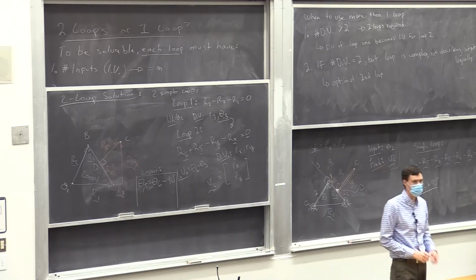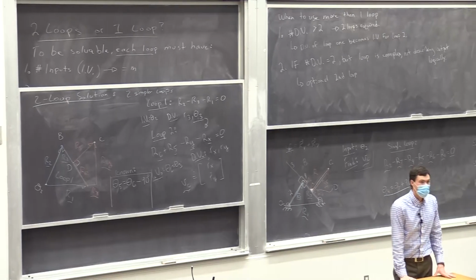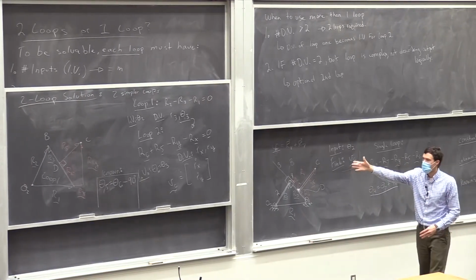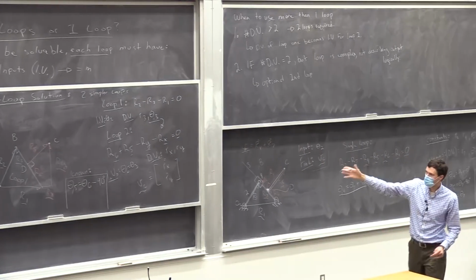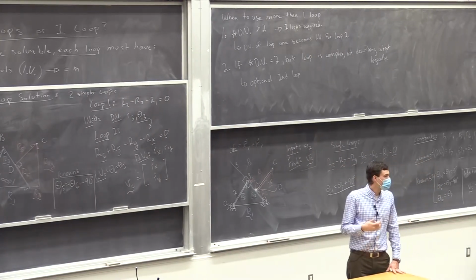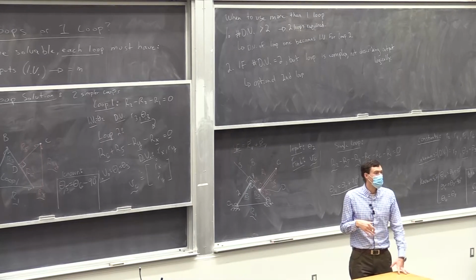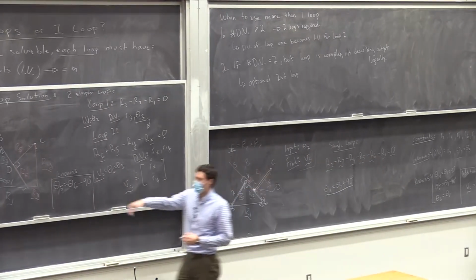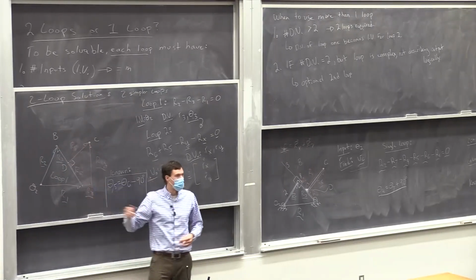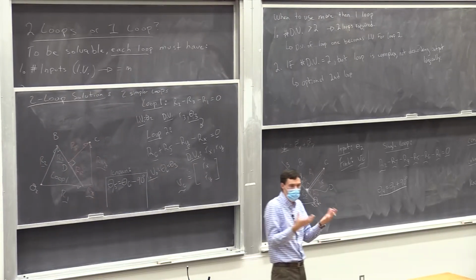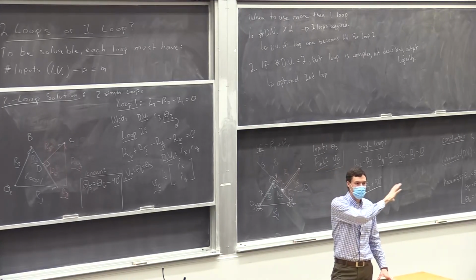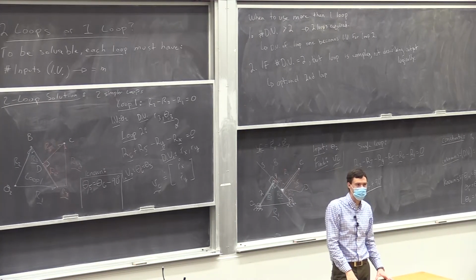Okay, any other questions about this? So as the designer, as the engineer, as the loop designer, you can choose. And you can kind of look at these 2 and think which one suits you. A lot of it may depend on what you already know. If you can identify a mechanism component that you've seen, like a single triangle, or a slider crank, or a 4-bar that you already have a prepackaged solution for, bam, that's your first loop. Add on to it for a second loop, and that's going to make for a quick, easy solution.